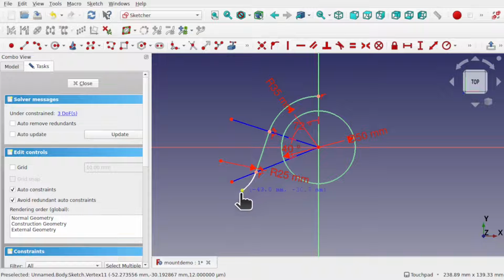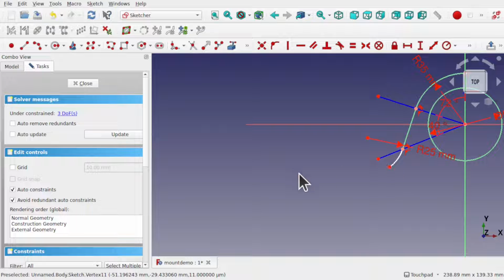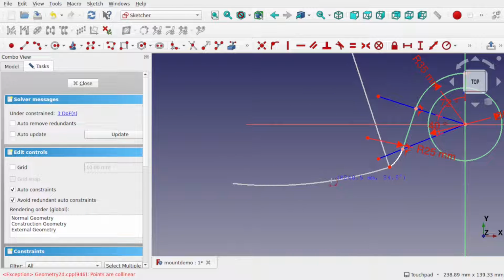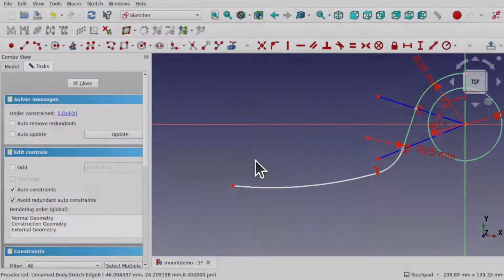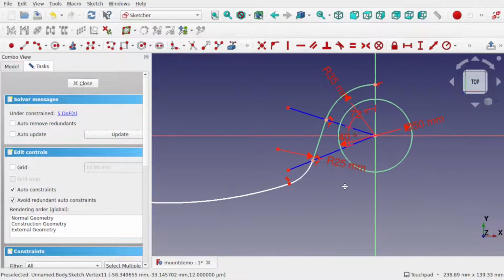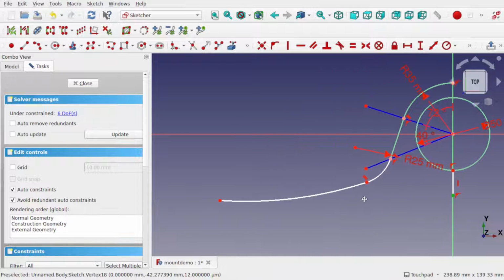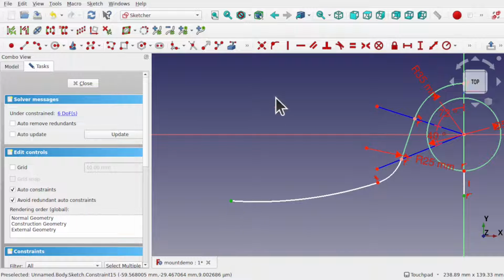I'm now going to create another arc coming from this one. This is going to be quite a shallow arc. It's going to travel over this way. Using the arc again, endpoints and rim point, we'll create another arc that sits here. Again, we add tangency between these two using the tangency constraint. And now I'm going to move over to the other side and add a line between here, this circle, all the way down, connecting up on this line. I'm going to take this point and the point of this arc and keep them in line. So those will be kept in line.